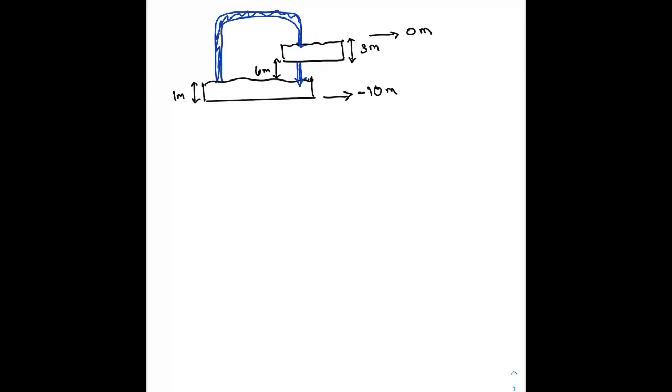Bernoulli's energy balance equation is the change in pressure over the density, plus gravitational acceleration times the change in height, plus the velocity of the water at two different points, point 1 and point 2, squared over 2, and that will equal the non-flow work over the mass plus the frictional heating factor.